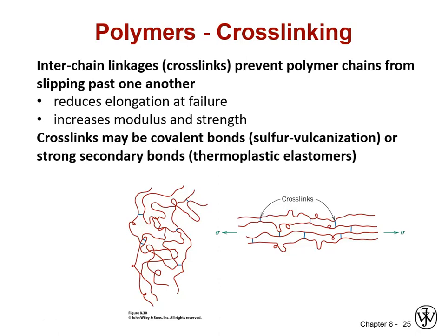We've pulled in everything from Chapter 2, again, our potential energy wells and equilibrium interatomic spacing, the genesis of those elastic strain fields. We had some crystallography. We pulled in the role of polymer structures. Our crystalline defects were front and center as our actual yielding mechanisms in the case of dislocation movement. And then we looked at different ways that we can put those all together and have them interact to stop dislocation movement in various different ways that will not compromise the material toughness.